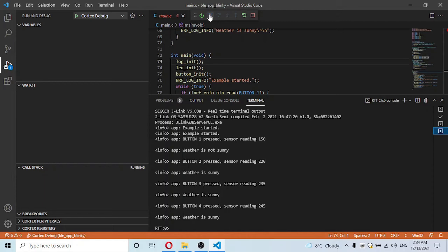Now, actually, I wanted to add Edge Impulse into Segger Embedded Studio instead of Visual Studio Code, but I was not able to do it. I will talk more about it at the end of the video and about what possibly could be done to make it work. But for now, this is the only way, at least for me, to use Edge Impulse and nRF5 SDK. So I had to use ARM-GCC, and that's why I should debug and see the logs over here as well.